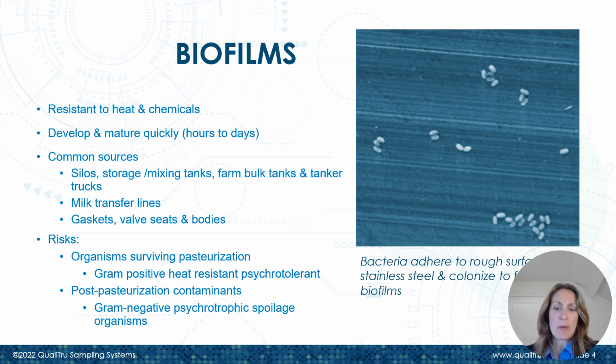Talking a little bit more specifically about biofilms, as this has been a hot topic for a lot of our partners lately, they're really a challenge because it's something that is really ongoing, and they're quite difficult to identify and difficult to manage. Biofilms are when you have a piece of polished stainless steel like this picture here. Stainless steel naturally has some rough surface. You can get different grades, but here's an example of one that's well polished. You still get bacteria clinging to the surface if it's sitting long enough or if you don't have good controls in place.